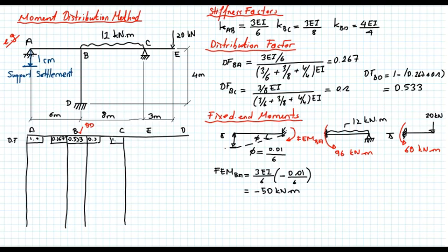All the moment will be carried by member BC. This is 0. So I got point E here. And at point D, I have a fixed support. So this is equal to 0.0. And again, let me put myself a note that this represents the distribution factor for DB. So that's the picture. These are the distribution factors.